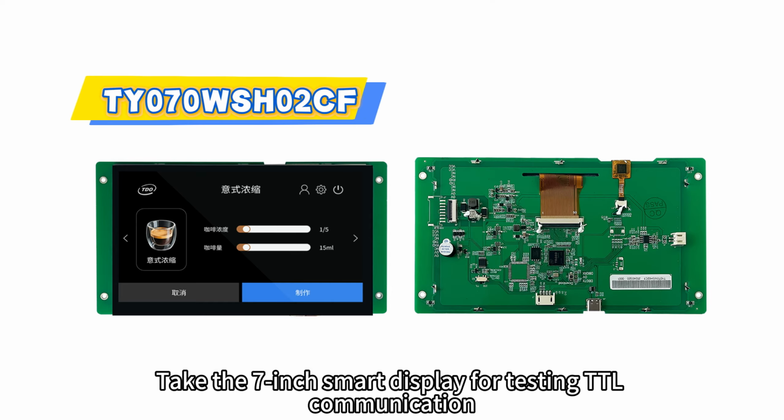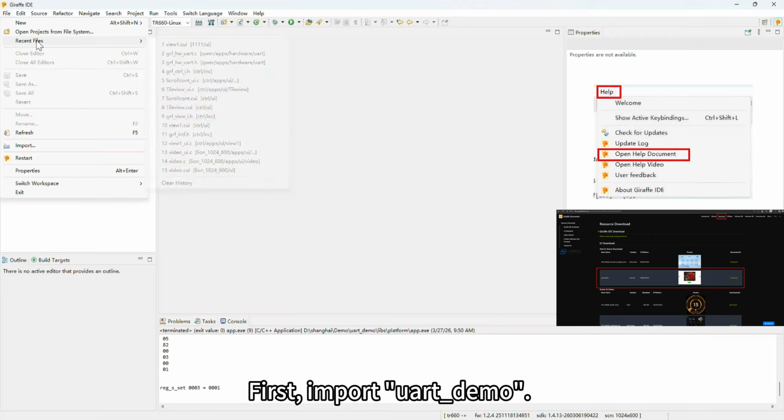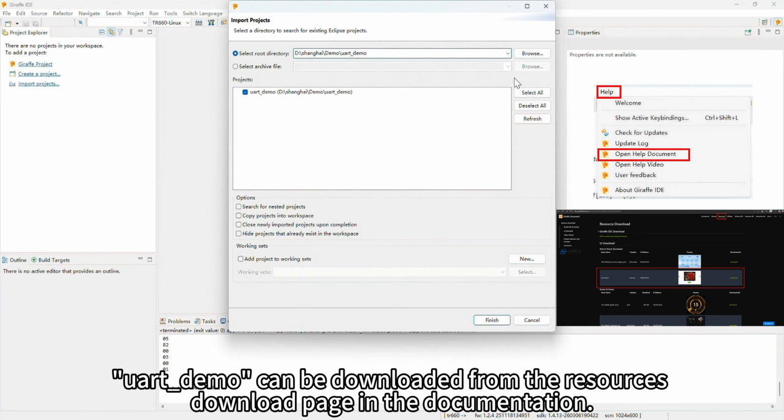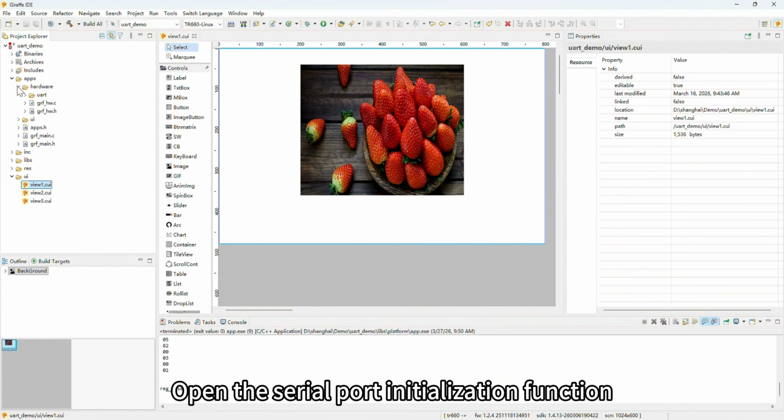Take the 7-inch smart display for testing TTL communication, and demonstrate how to debug serial communication. First, import Uart demo. Uart demo can be downloaded from the resources download page in the documentation. Open the serial port initialization function.